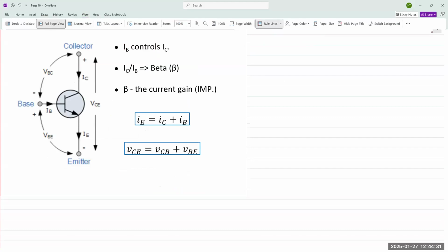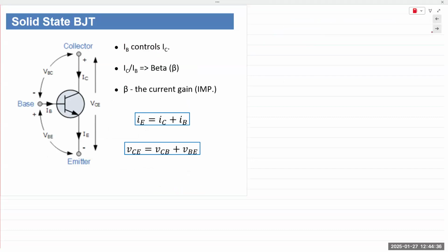Remember the 2 subscript notation, meaning voltage measured at the first subscript with a reference at the second one. VXY means you're taking your meter and connecting the positive terminal to X and the negative terminal to Y.